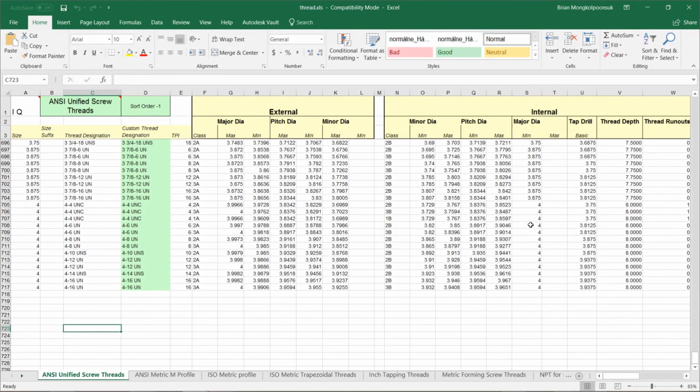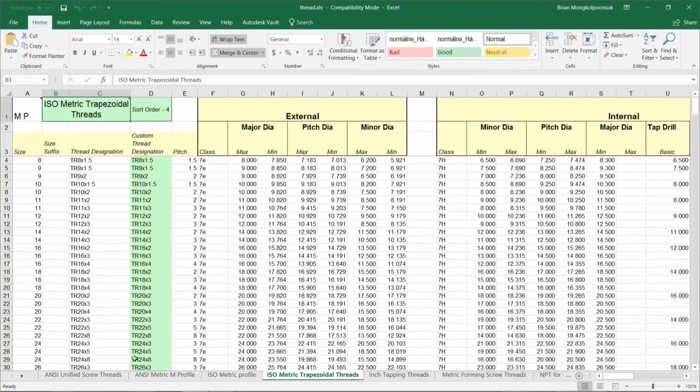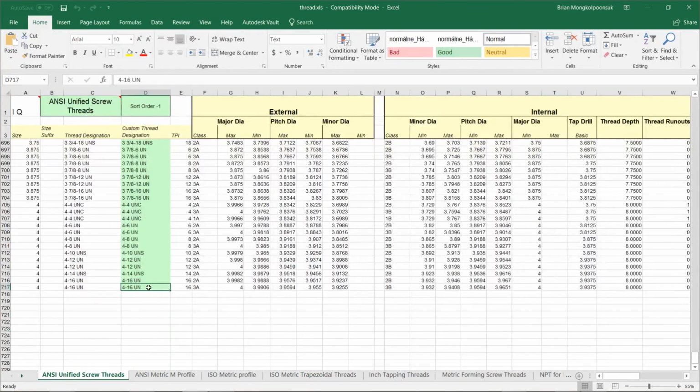This pulls up a file that was downloaded when you downloaded Inventor. And this is why you need Excel when you download Inventor, so that you can reference this sheet. It has all of those thread types that we saw in that thread window. You can edit them, whether it be the name or the major diameter type. There's a particular formality that goes along with this, and I have that document as well that I will post in the chat room at the end.